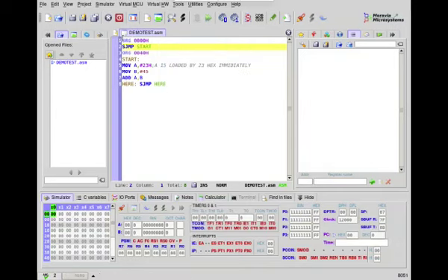The first instruction is not an executable instruction. It is only an assembly directive. ORG means originate from 0000 address. SJMP is an instruction that will jump to a label start. So where is the label start located? At address 0040. So why are we skipping the addresses from 0000 to 0040?